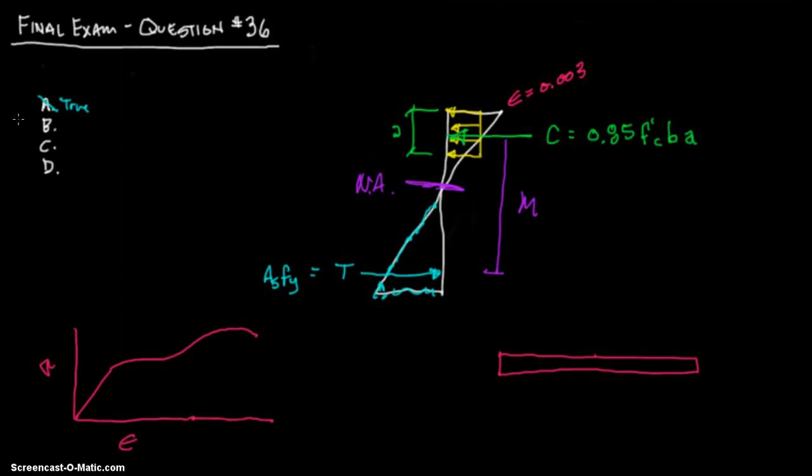And so let's say you overstress, you yield the steel. Well, it's right here. So that steel is starting to, it has failed for design. You have failed that steel, and it starts to lengthen, and it lengthens. And then when you let go of it again, it follows the same slope right here. It follows that same slope, and it comes down.